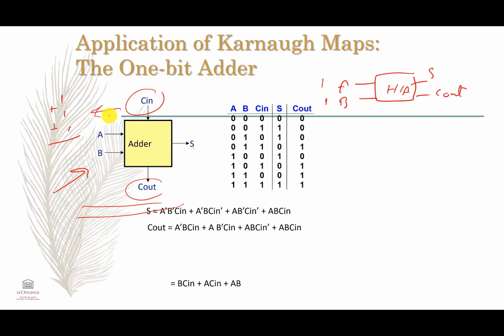design an adder, and that adder is symbolized by this box, and this box has to be replaced by some logical gates, so we don't know them yet. So remember, the first step to design any digital circuit is to construct the truth table. So this circuit has, look at this, 3 inputs, A, B, and C in, and has 2 outputs because we need to calculate the sum.